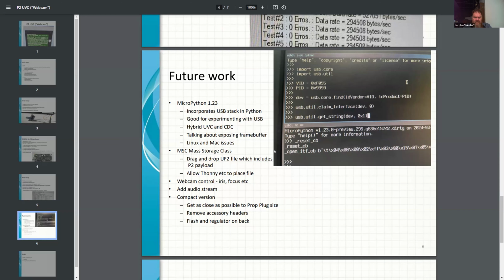Yeah, some of the Python programming tools like Thonny and perhaps Mu as well have the ability to send the UF2 file from within the IDE directly into the controller. So they have like a save as, but instead of saving it on the PC, it can save it onto the mass storage device directly. It's equivalent to flashing the microcontroller, but in a way which is a bit more intuitive, I guess, for people who are used to dragging and dropping files, but aren't yet used to programming flash with tools. So yeah.